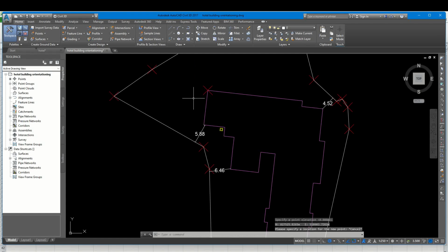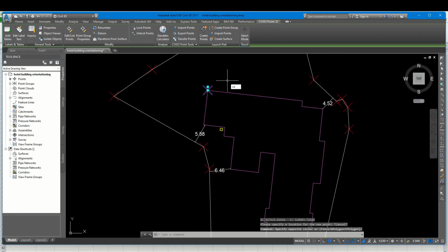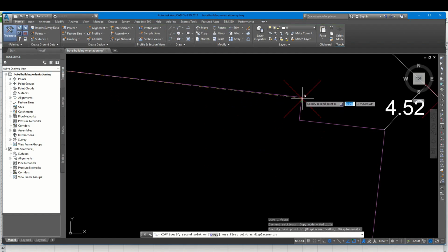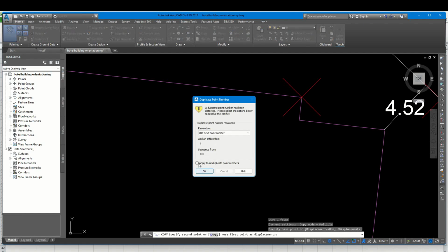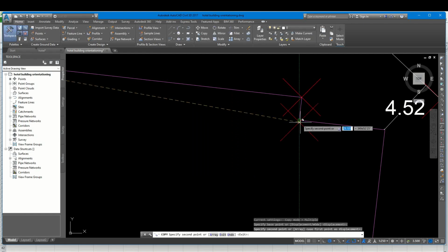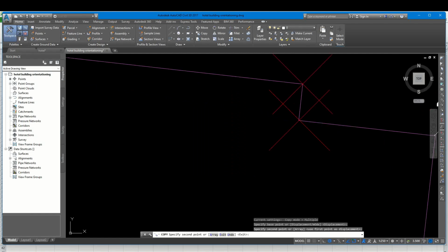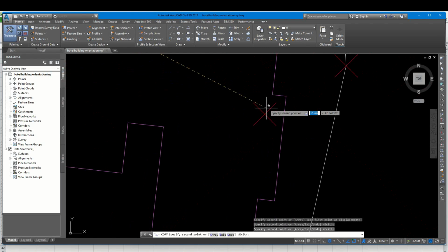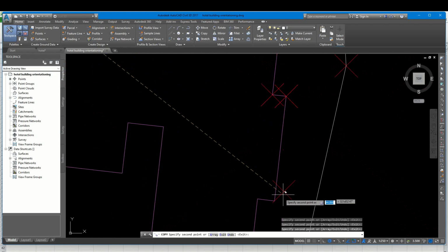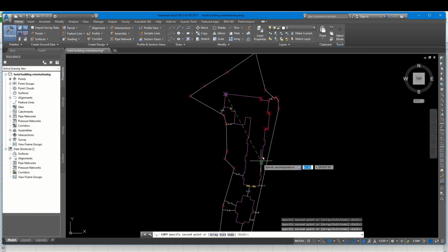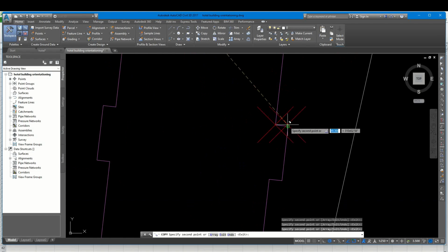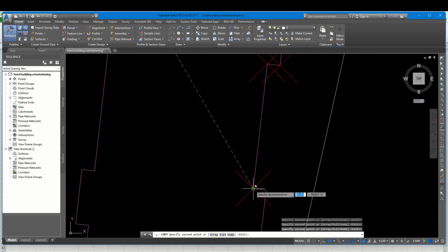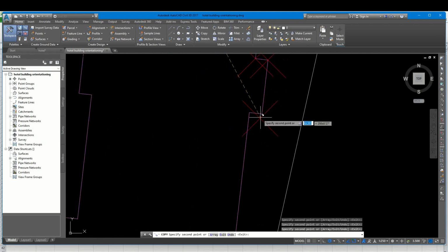So let me just copy this point, copy. I'll place it at the changing positions. We're only extracting coordinates, changing positions. Make sure you're very close to the end. The resets, changing positions. You place your points, and this is the information the surveyor will need to feed into his own total station.